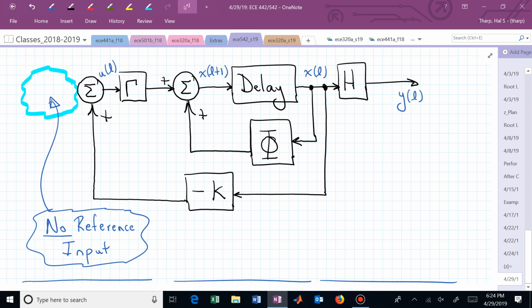If you're doing Kalman filtering for your project, then you're basically trying to estimate x. A Kalman filter a lot of times is used if you have noisy measurements, and it does a pretty good job of cleaning up or getting rid of the noise in your signals or in your output, and now you can use this cleaned up signal to control your system.